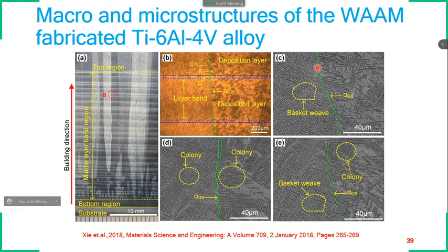Especially for a material like titanium 6Al-4V, once we fabricate, especially at the molten state, the metal will undergo transformation. Actually, Ti-6Al-4V is an HCP alloy. That HCP alloy will get converted into the BCC phase above the beta transformation temperature. Okay, because it is an alpha-beta alloy.